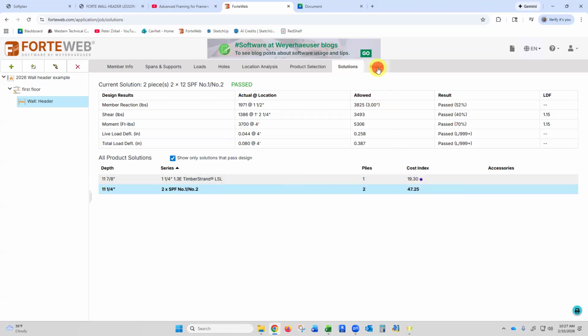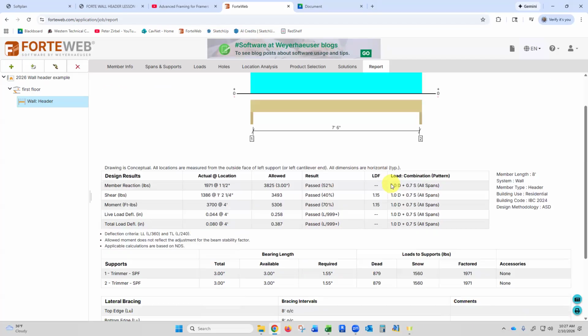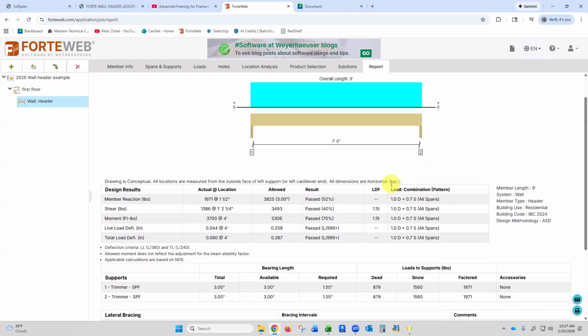And then here's where we get our report. We're going to still highlight the 2x12s. So you can see the percentage of load we're using. It's a little overkill probably structurally, but that's just the way we typically roll. We just typically put 2x12s everywhere for Habitat. And then if we want to go ahead and make our PDF to turn in on the assignment, we click there.